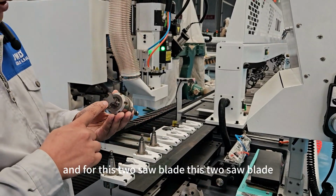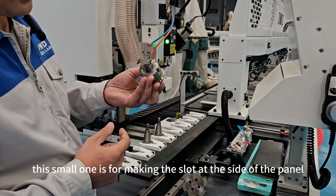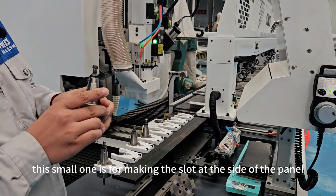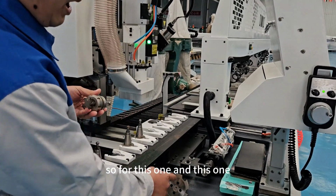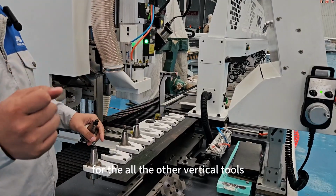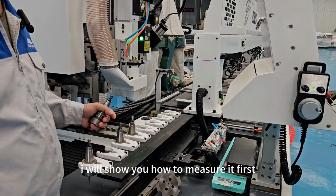And for these two saw blades, this small one is for making the slot at the side of the panel. So for this one and this one, we cannot use the tool sensor to measure. For all the other vertical tools, we can measure it. Later, I will show you how to measure it.